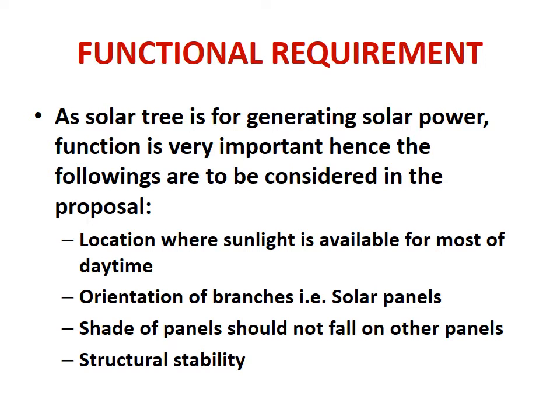One is location, where sunlight is available for most of the daytime, and then orientation of branches where solar PV panels are installed, so that they get sun during most of the time of the day. Then shades of panels should not fall on each other, so that the generation is optimum. And then we are to see the structural stability of the structure, that is also important.